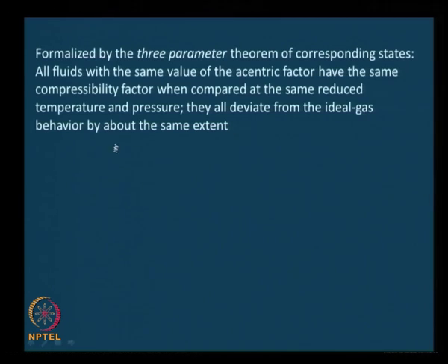This was formalized by the three-parameter theorem of corresponding states: all fluids with the same value of acentric factor have the same compressibility factor when compared at the same reduced temperature and reduced pressure. In other words, they all deviate from ideal gas behavior by about the same extent.